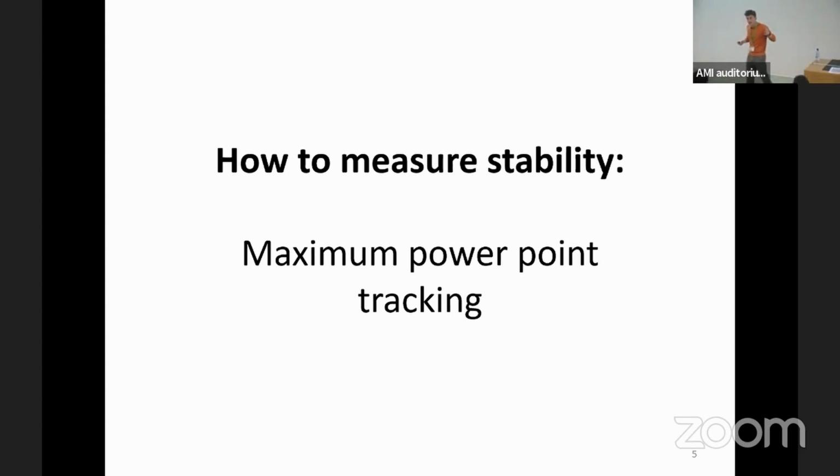First question is, how do we measure stability? This was kind of anticipated this morning. I think it's very important, still unclear. One of the first understandings about measuring stability of perovskite is that we need to measure the device under maximum power point tracking, which means the device has to be illuminated and a voltage applied around the maximum power point.